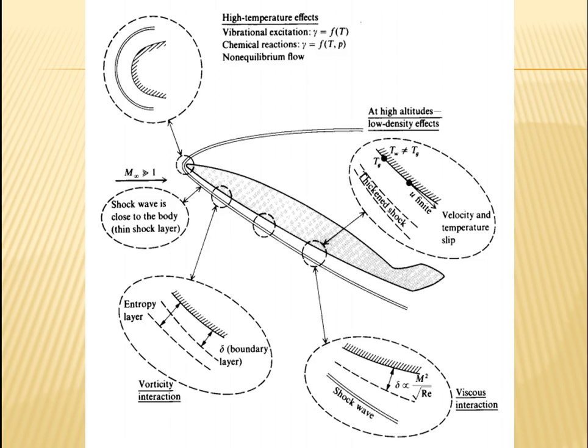In subsonic flow, compressibility is almost ignored, and viscosity is very important. In the supersonic region, we normally ignore the viscosity and believe that the flow is compressible, and the compression phenomena and the shock appearance are very important there. But actually both compressibility as well as viscosity are always available, depending upon their relative importance and relative strength, which start affecting the flow parameters. We normally account for them, and we call the flow compressible or viscous flow. Something similar happens here also. These phenomena are always available.